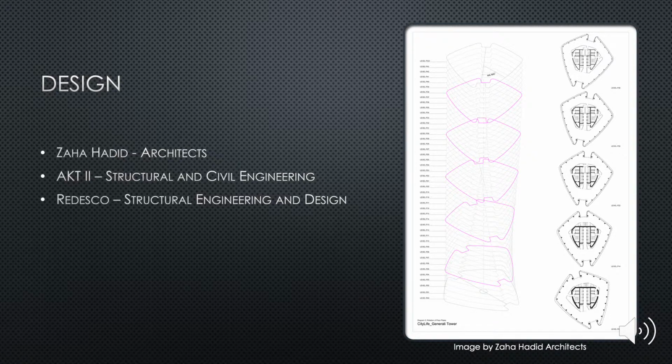Parametric models were used to consider buildability, cost and robustness of detail. The angle of rotation was controlled carefully with a framework of rules to ensure the structural system could be controlled and allow for facade to core floor plates to be developed.